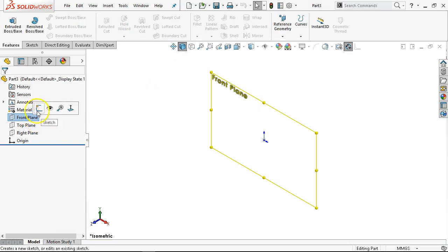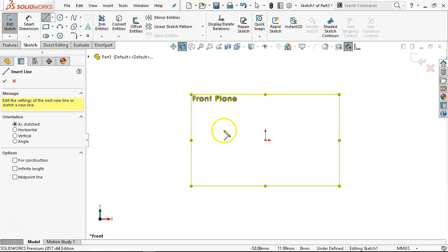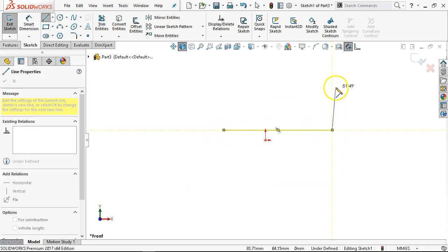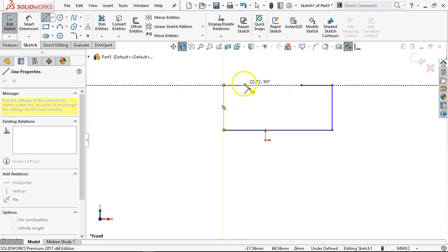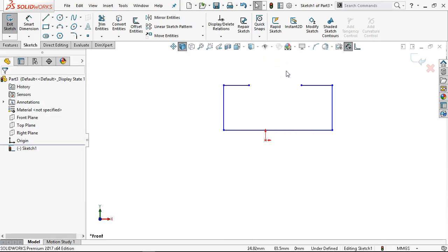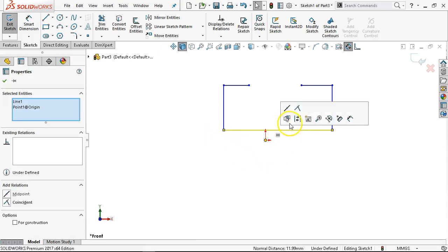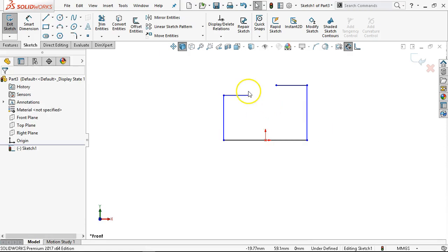All right. So front plane sketch, I'm going to put this on the midpoint. And one of the conditions for a thin feature is that all of these lines have the same thickness. All right, so we're 10, 10, 10, don't see any other values. And I mentioned before that we kind of get in the habit of putting the lower left of our sketch on the origin. Keep in mind you don't have to. It's not a requirement. I can go to a midpoint.